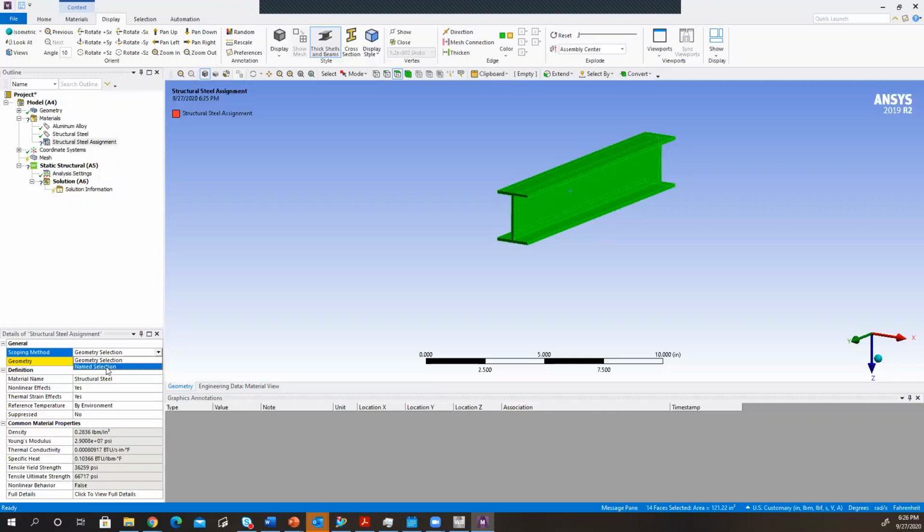And then to select them and to add material, instead of selecting every individual one, you would just call out that selection. And this is what it's basically telling you right here. If you have a particular selection of, for this example, bolts, you just select them and it's going to automatically select all 24 of them, and you could apply that material to all 24 of them.